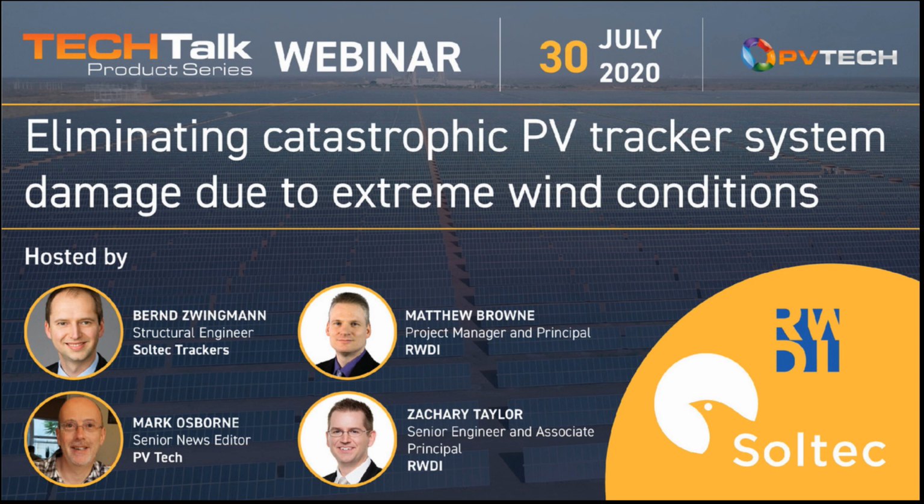In case of bifacial modules, it's more complicated, because when you get too close, the additional yield that you get from the ground reflection decreases. So typically for bifacial projects, we would choose a bigger distance between the rows, but this also depends on the location and on the ratio between direct and indirect radiation.